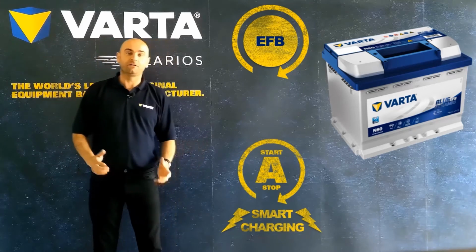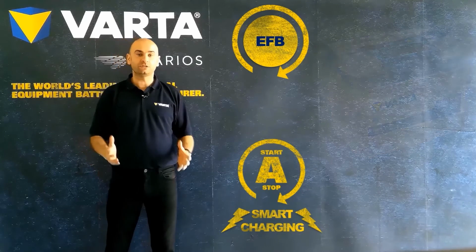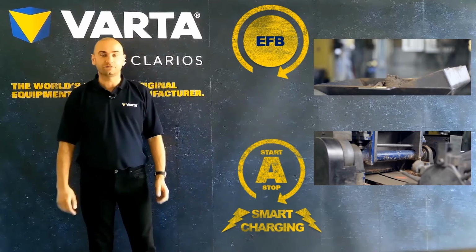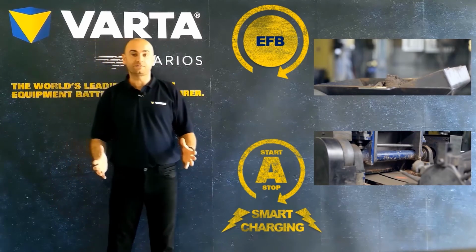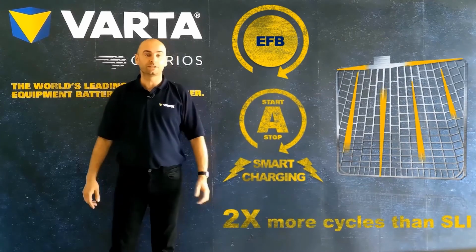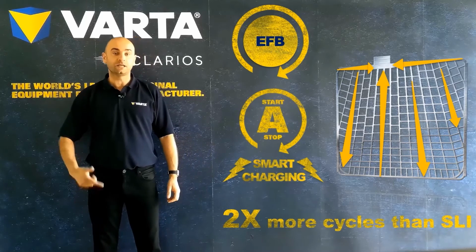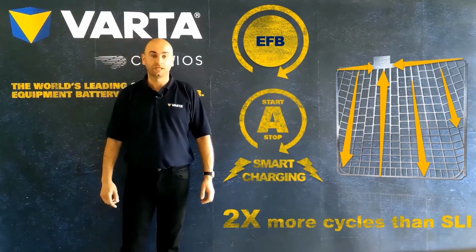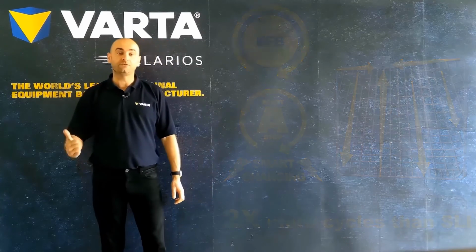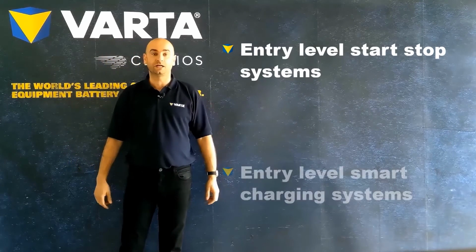EFB batteries are a further development of conventional lead-acid batteries. The materials used on the surface of the positive plate guarantee that the EFB has a longer service life. EFB batteries have a low internal resistance, plus have twice the number of charging cycles in comparison with conventional SLI batteries, as well as a high load capacity. EFB batteries are suitable for the power supply of cars with entry-level start-stop systems and/or entry-level smart charging.